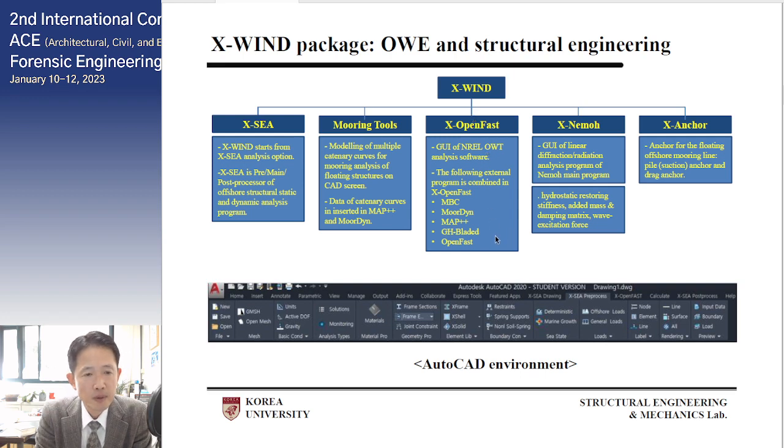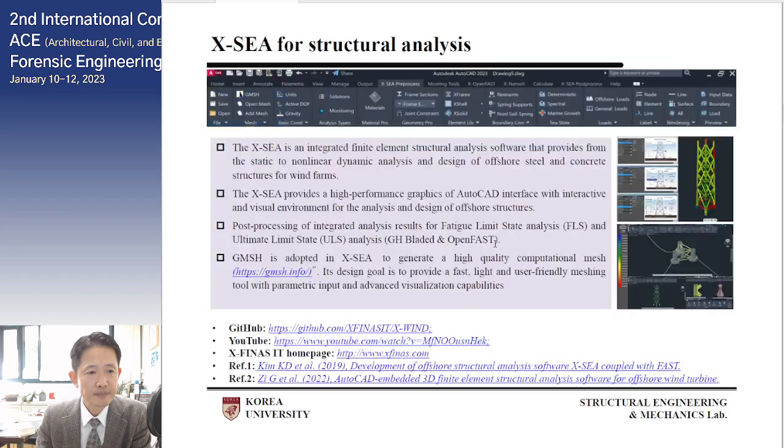Another noticeable point regarding X-Wind is that it is implemented in the AutoCAD environment to maximize the graphical user interface. To build a model for this analysis, we don't have to use any separate preprocessor from the CAD program. We just use the AutoCAD environment, build a computational model from the objects built in AutoCAD, and then run the finite element analysis.